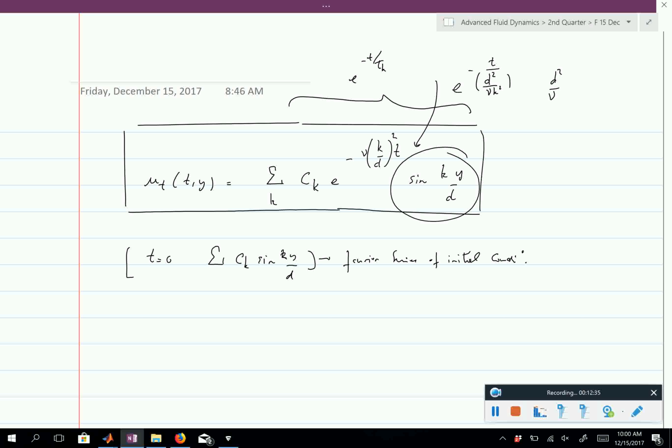When the wavelength is short, the short wavelengths will be diffused much quicker. If you have a very small gradient in velocity, then the diffusion will act smaller. Diffusion has two things to think about: the diffusivity, but also the gradients. The sharper the gradients, the faster the diffusion. It's the same with temperature. The sharper the temperature gradient, the faster it's going to get initially flattened out.